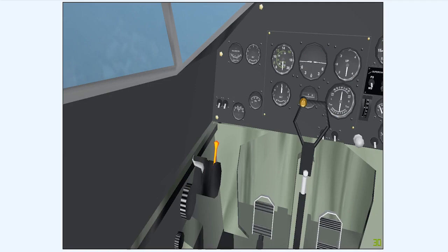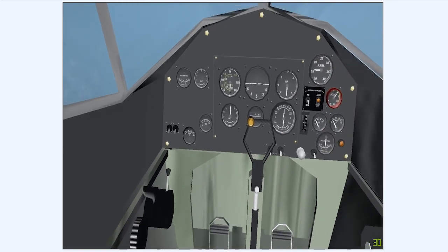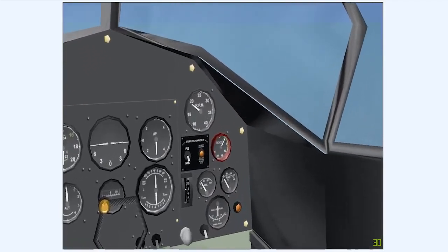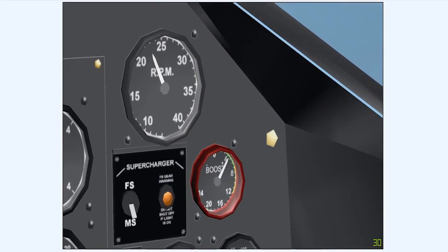Thus, the propeller pitch control lever can be said to be an engine speed control, and, as the supercharger impeller is driven by gears from the crankshaft, any change in engine speed will result in a corresponding change in the speed of the rotation of the compressor impeller. Having said this, if the engine is fitted with an automatic boost control unit, then the boost pressure reading will essentially remain constant at whatever is set by the throttle lever, while the engine RPM changes independently.